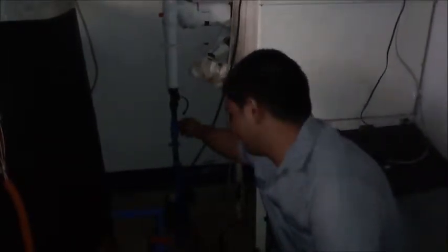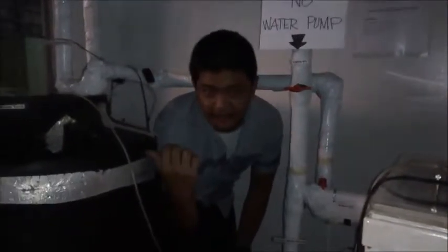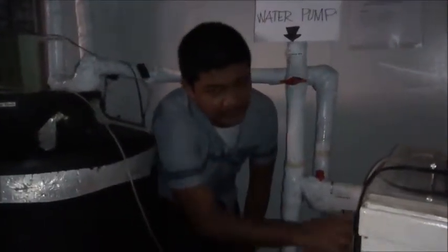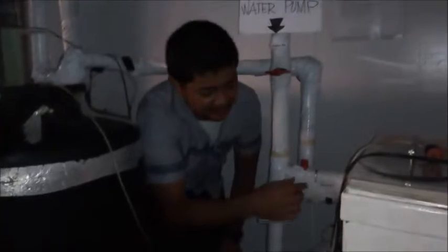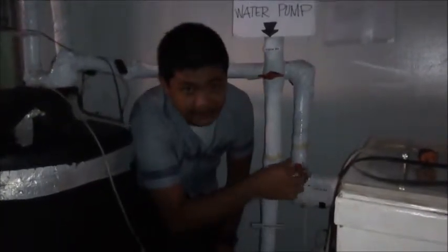reaches its required temperature. Now in the discharge port of the chilled water, we will change the state of the first valve to fully open. Now we will change the state of the valve next to the flow sensor, this one, to fully open. To allow the flow from the chilled water tank into the cold storage, we will change the state of valve number 3 to fully open.